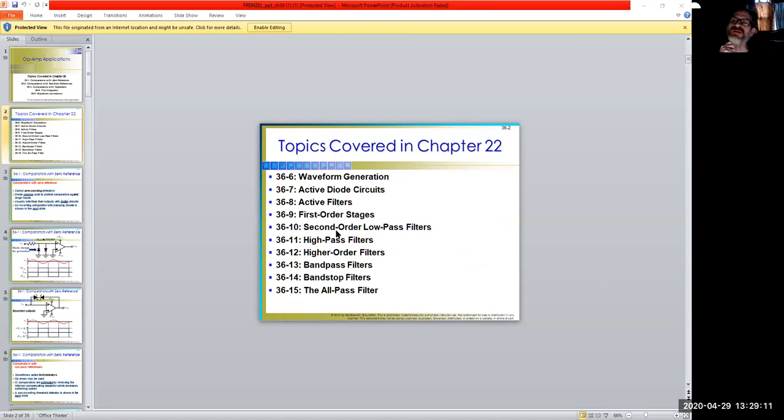That's another thing that op amps are extremely efficient at and widely used as filters, both low pass and high pass. And how would this differ? So you've done it in AC models, where you've done high pass, low pass, all pass, band pass filtering and everything using RLC circuits, combinations of resistance, inductance, and capacitance. But those types are what they call passive circuits. So really, you just have components sitting in there, and based on their values, they're sitting idle until they react to signals coming at them.